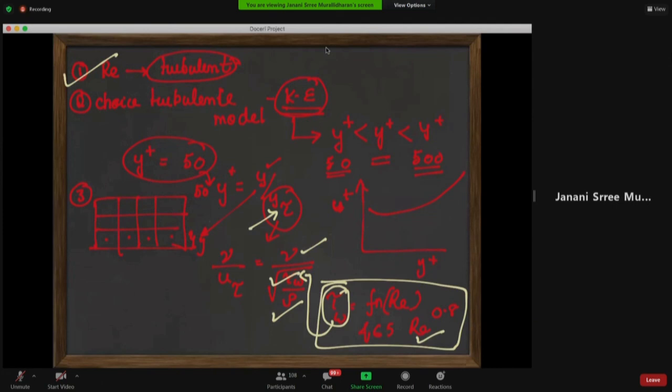You said I'm going to use K epsilon, which is I need a rough Y plus of 50. So I know a Y plus, I now know a Y tau, so I can calculate the Y. So for my first step to mesh with just pen and paper, I do have an estimation of my first mesh size that I have to do. Okay, just pen and paper, and it all hinges on what? This particular empirical expression of tau wall that you have taken. Okay, but that is generic for a very, very standard case.